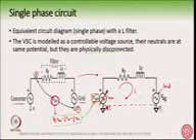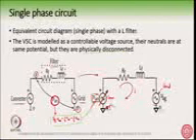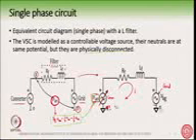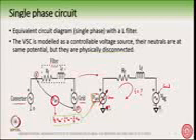I can write it only when I connect it, but I have not connected it. Although I know that these 2 points are at the same potential, I will not connect it because they are physically disconnected. But if I want to know what is I, I have to assume that they are at the same potential and there is a path for the current to flow. Only then can I write the KVL equation.